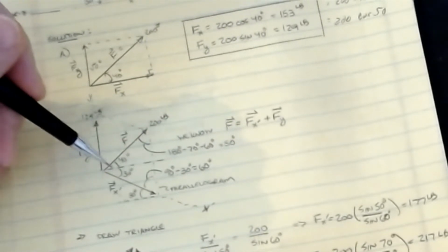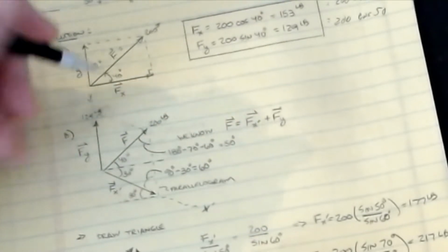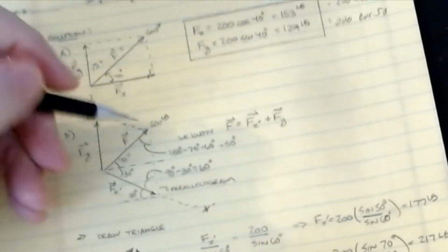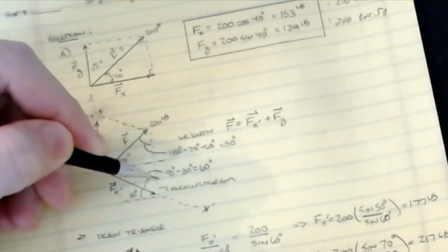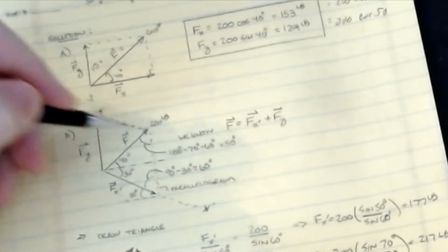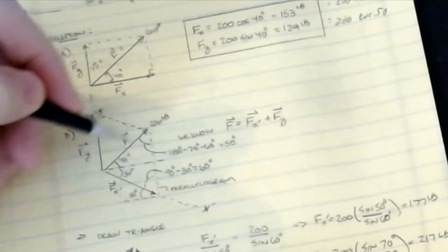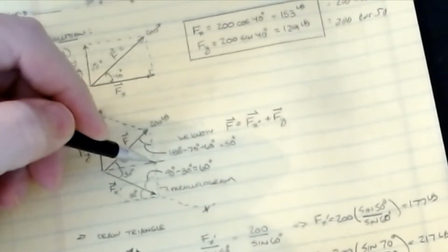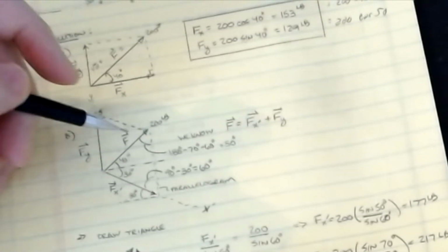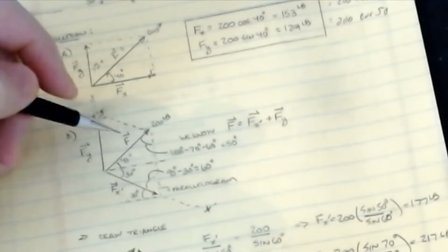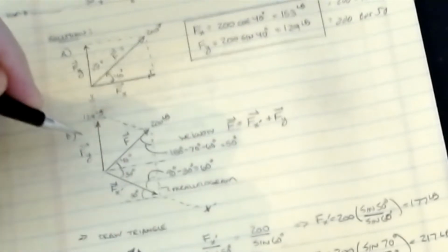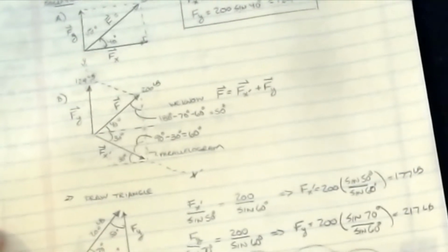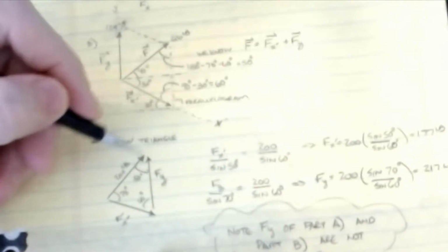So if I construct a parallelogram off of this, I can construct a parallel line across the top through the head of that resultant, and then I can construct the vertical parallel to the y guy there. You've got your parallelogram, and this is the resultant across that parallelogram. Now, our F vector is still F of x prime vector plus Fy vector. And so we can play around with our parallelogram and pull out one of those triangles.